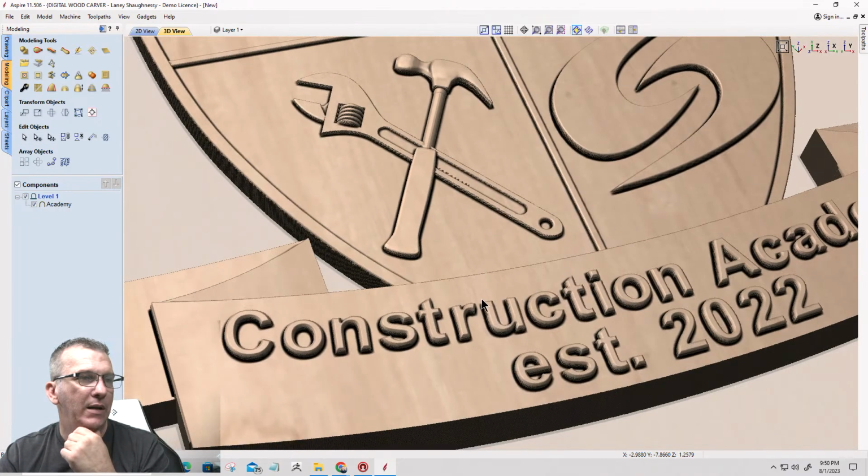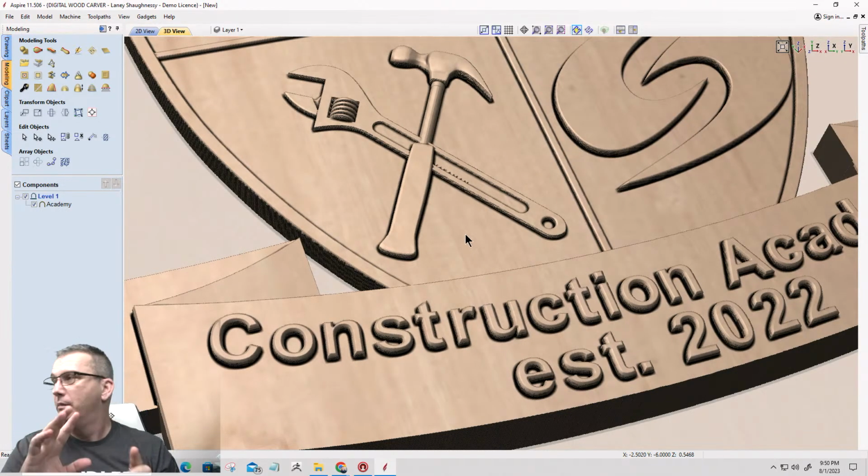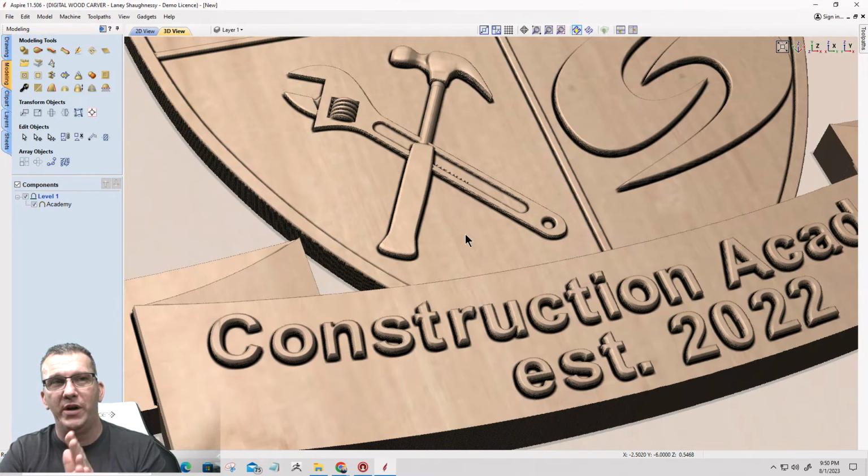Yeah, that tells me right then and there, if you by chance imported your model into a low resolution and you wanted to change the resolution, re-import the model, because changing the resolution did not clean up the edges the way they should have been cleaned up.